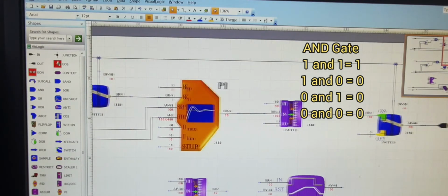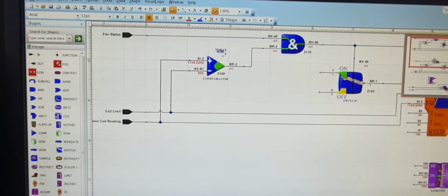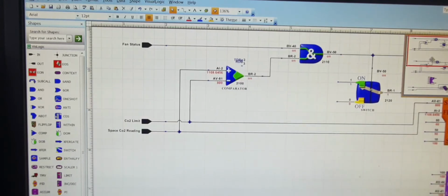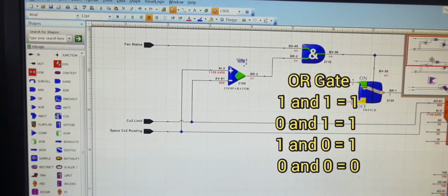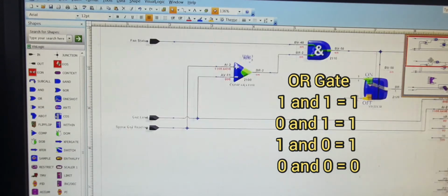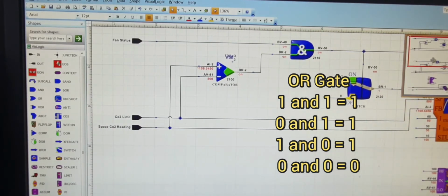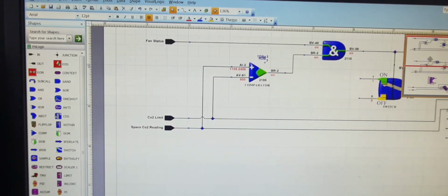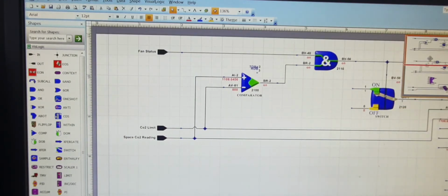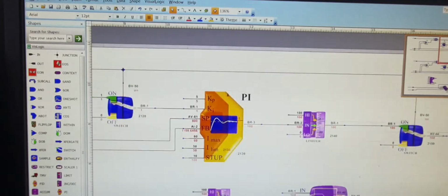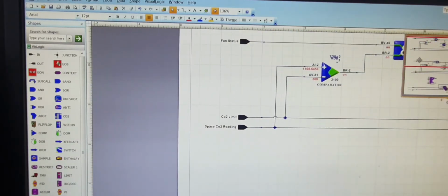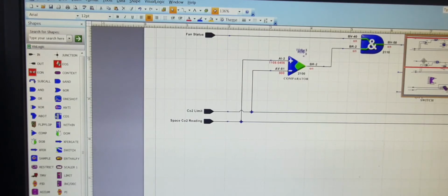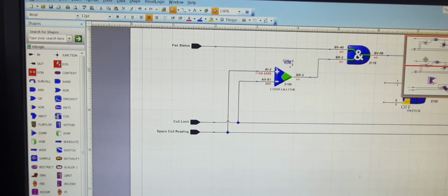Now, as we were discussing earlier, these CO2 levels do indicate there's not proper ventilation in that particular space. The office or hall or whatever area you're working on is not having proper ventilation. So immediately you need to rectify and take action. And this is what we're programming in the BMS with our Alerton system: we need to open up the damper. So this is the strategy we have written. I keep saying strategy because I was working in England for Trend, and in Trend, you write a program logic and you refer to it as a strategy.